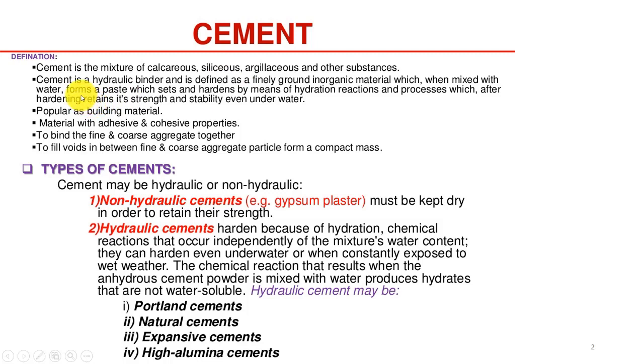Secondly, cement is basically a hydraulic binder. A hydraulic binder is a type of binder which can gain strength in the presence of water. Without water, it retards its strength. It depletes its water within the mix. It is compulsory to have water for its hydration reaction. So cement is a hydraulic binder. Both cement and lime are hydraulic binders. We will discuss lime later.